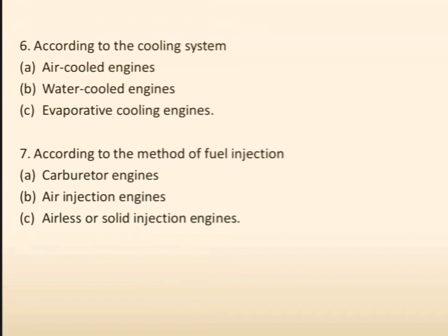And evaporative cooling is the enhanced version of water cooled systems. Now in evaporative cooling engines, water in the liquid phase is introduced into the cooling jacket of the engine, and a control system allows this water to boil off and become vapor. The liquid phase and the vapor phase are separated in a separator tank, and the vapor is returned to the liquid state in a condenser.